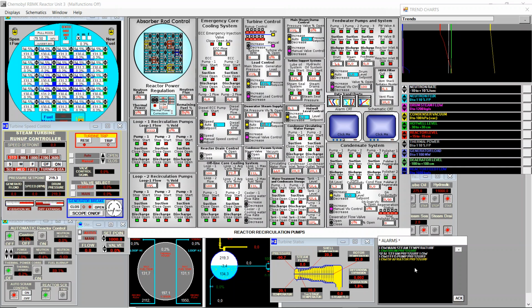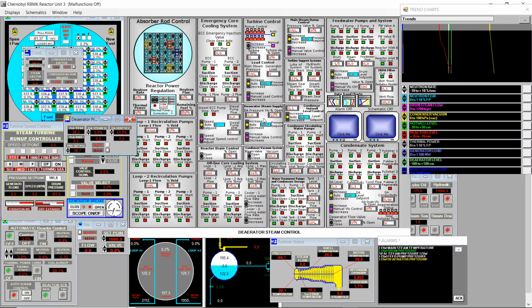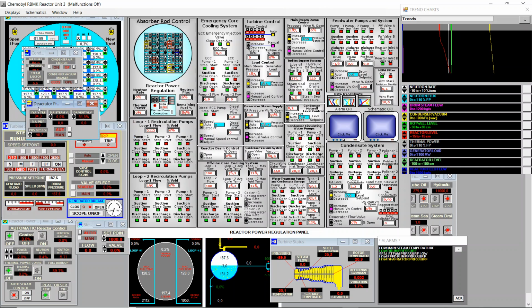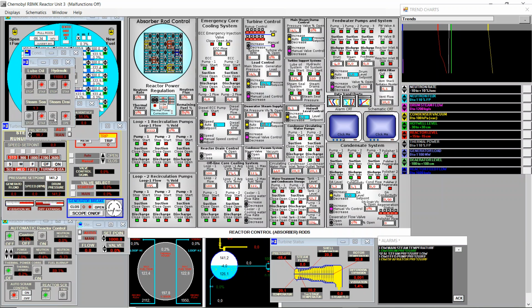Okay. Condenser vacuum and the aerator pressure. I will break the vacuum breaker. I will open it. But first, I think I need to stop the steam seal from the turbine because it's already at 0 RPM. So I stop the steam seal.